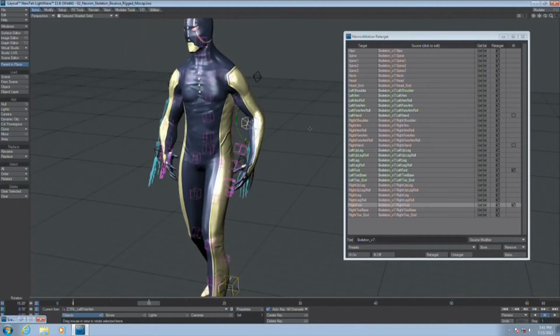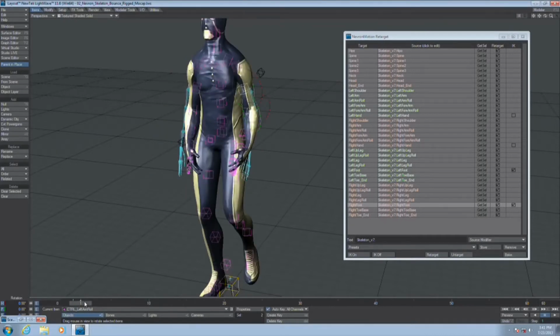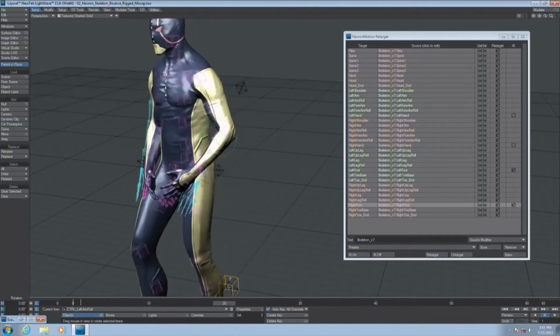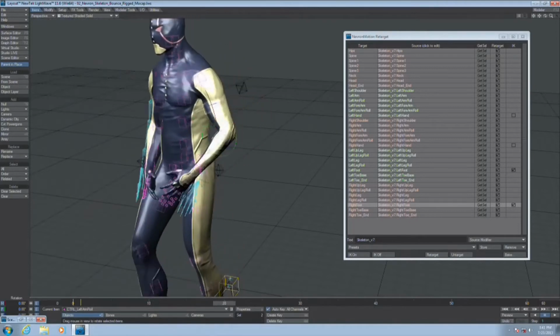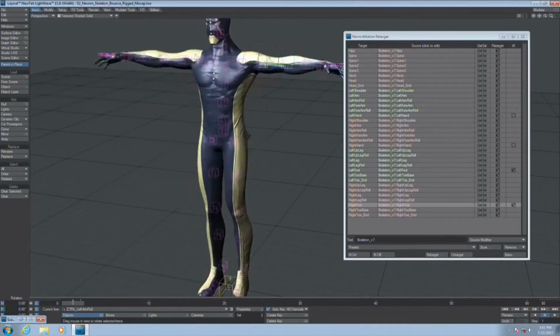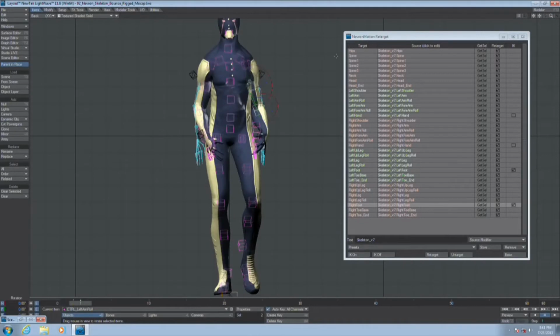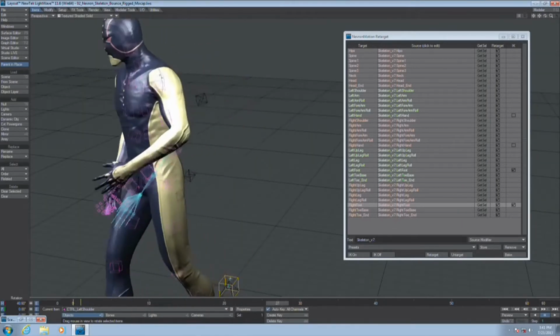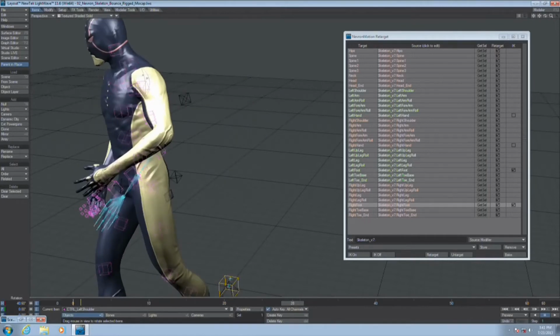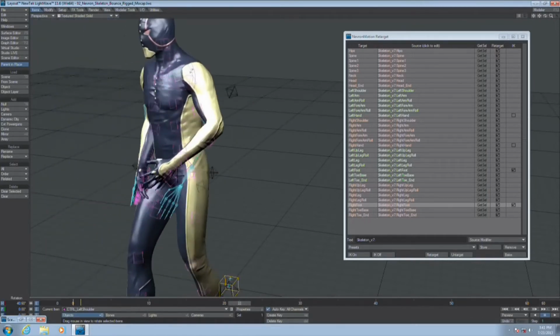I'm going to copy these keyframes to frame 1, because I made the modification at frame 10. When you make this modification, it's not changing the original motion capture data, it's just augmenting it, adding on to it. It's like a layer of animation over your mocap. It's non-destructive, of course. Another thing we can do is correct the position of the shoulders, to make them a little larger. And even in this case, the change propagates through the whole animation, which is really useful.